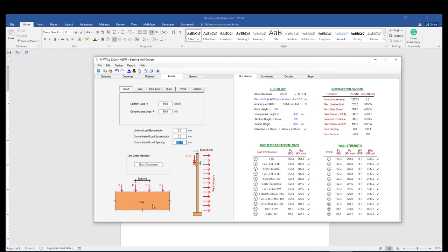It means we have a wall, and here is the primary or secondary beam which comes to the above of this wall. Here is a lintel beam, and it comes to above of this. So the spacing can be 1.2 meters or 120 centimeters, or it can be extended. It's based on your project.